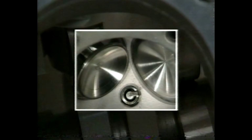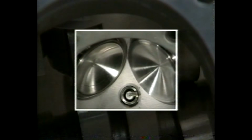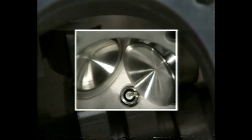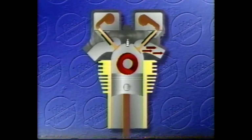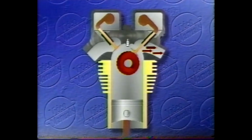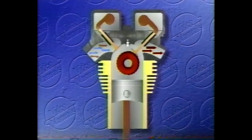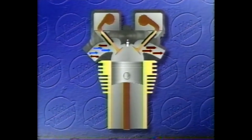For example, the longer the duration, the higher will be the RPM needed to produce maximum horsepower. At the same time, our power in the lower RPM range will be reduced. The longer the valves remain open at low RPMs, the harder it is for our piston to compress the fuel-air mixture effectively. Lack of piston speed and excessive duration result in poor volumetric efficiency, thus reducing the compression or cylinder pressure.